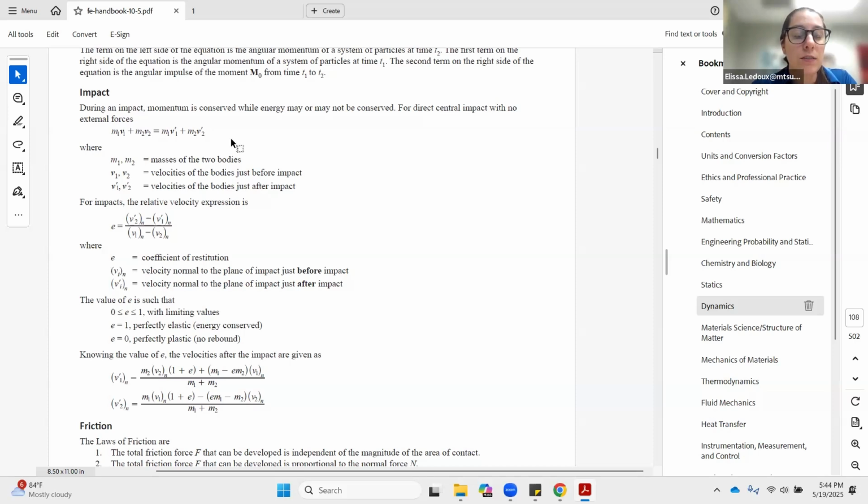In the y direction, the velocity would be conserved, and that is called the plane of contact. So e only works in the x direction, which here they're calling the normal direction, or the line of impact. So you would use this formula with post-collision speeds for object 2 minus object 1 over object 1 minus object 2.